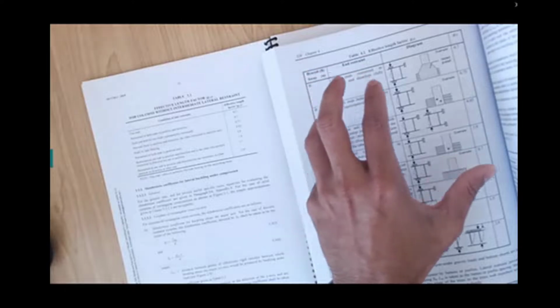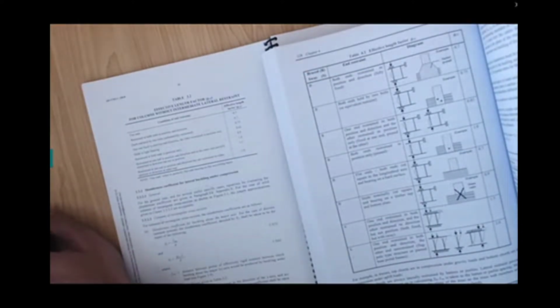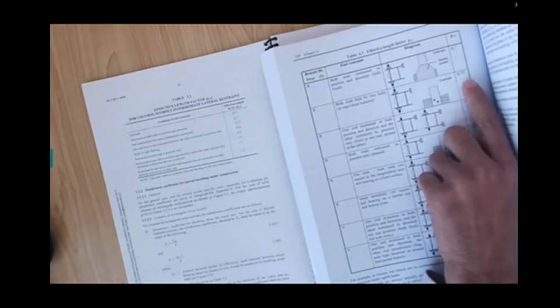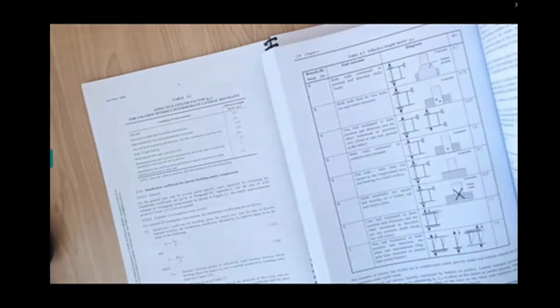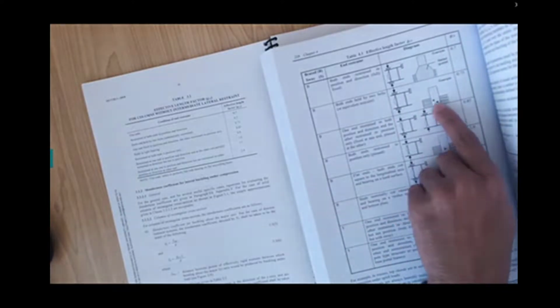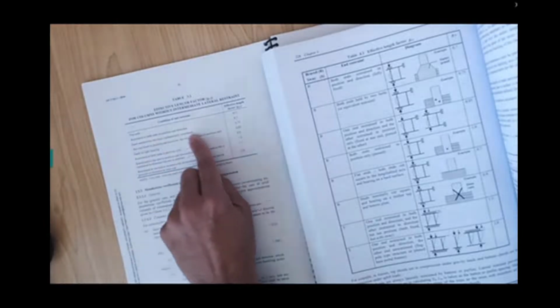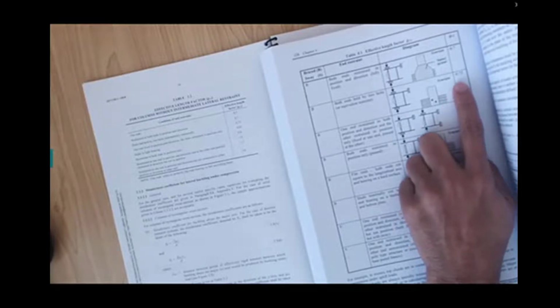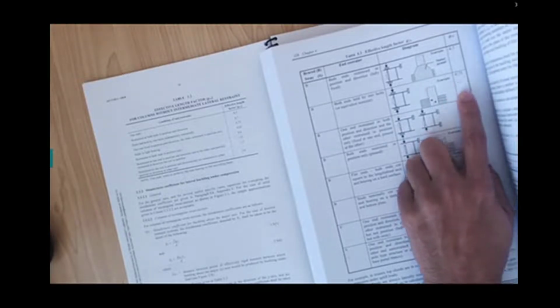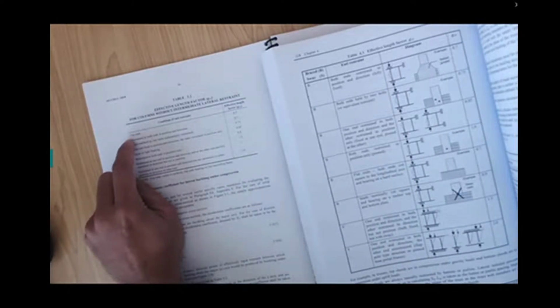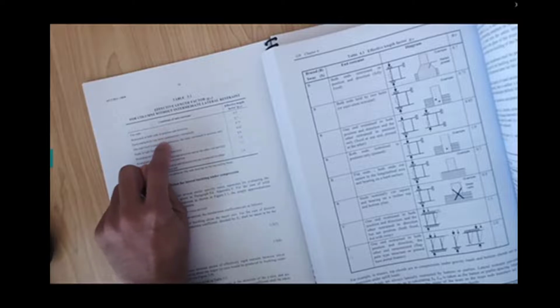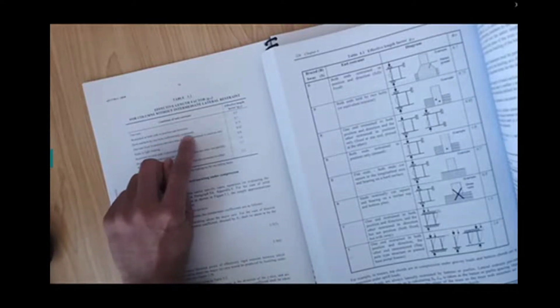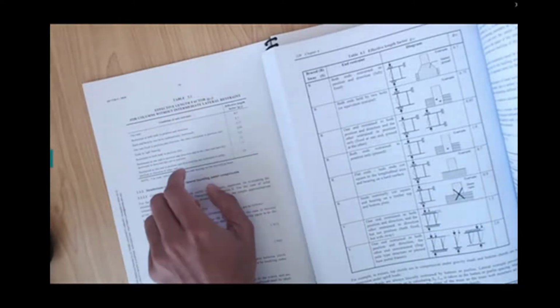You can see it's close to 0.7, but it's slightly recognized that your bolts at the two ends are not exactly the same. This is again part of the brace column, so your columns will not be moving away from their positions. I hope you understand fixed, and each end held by two bolts, some rotation allowed. It says substantially restrained, 0.75.